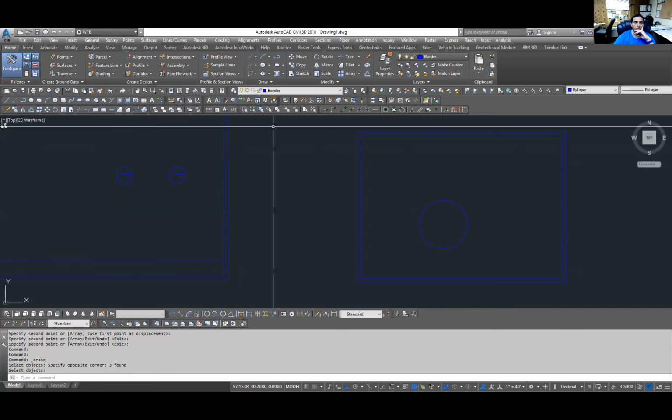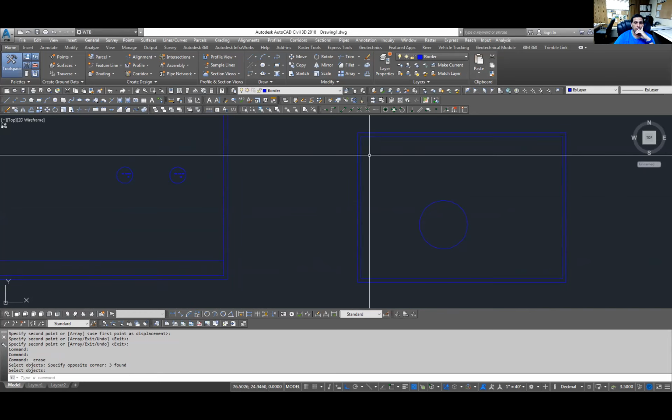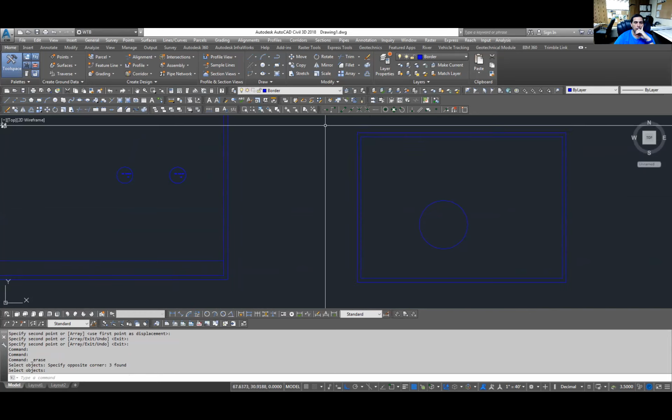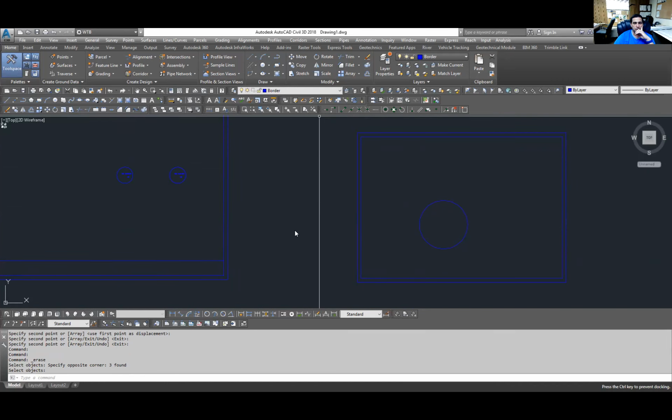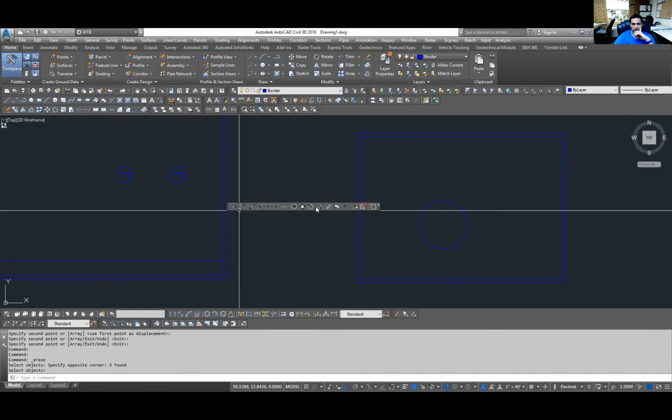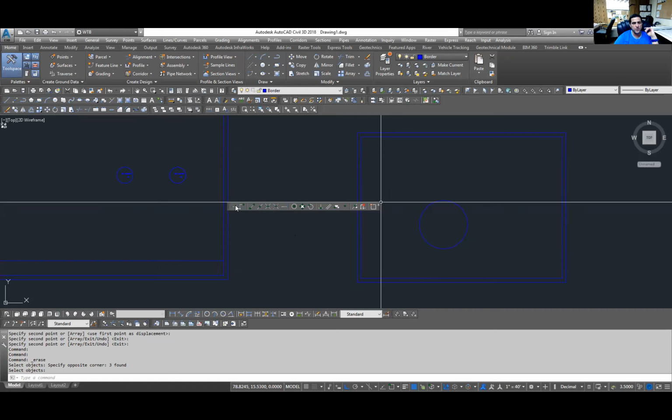Some other helpful tools are called OSnaps. So OSnaps look like this. What OSnaps are: you have endpoint, midpoint, intersection. Apparent intersection is if you have two lines in three-dimensional space. You can see them overlap, but one in its Z coordinate is closer to you than the other.